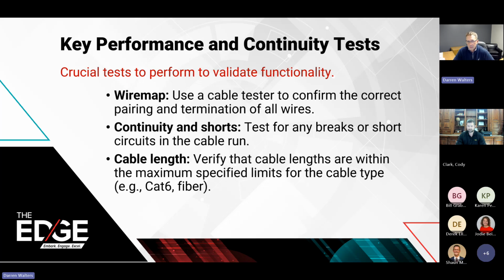Continuity in shorts, it tests if there's an open or a break. So if pins 2 through 8 are connected, but one's hanging loose on one end, then it's going to show us an open, and we can verify that it's all connected properly.